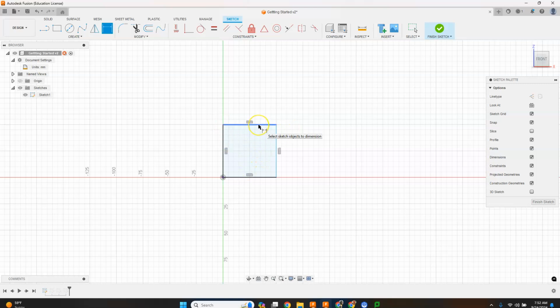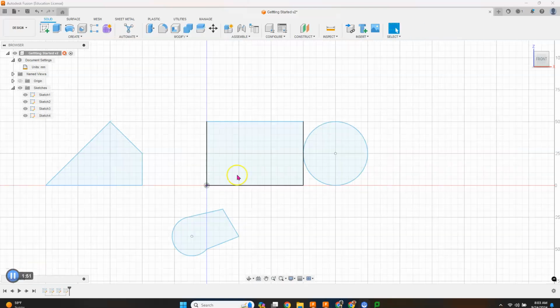So just for this right here, if we select this and pull it straight up, it says 50. If I drop that down, now what I can do in there is I can enter a new piece of data. Maybe I wanted to call it 75. And the number is not really important for right now. It's just knowing that we can add dimensions and edit dimensions from those pieces that way. Once again, if we're done editing dimensions, we can hit the check mark to finish those.